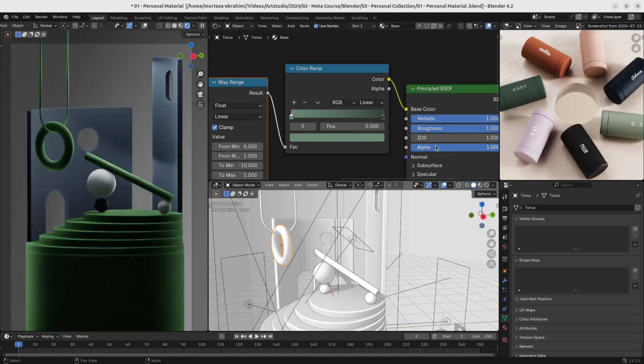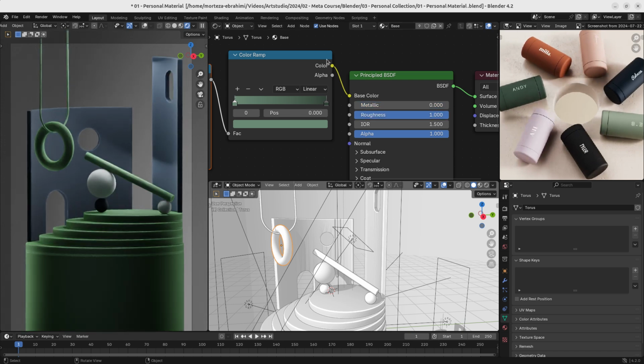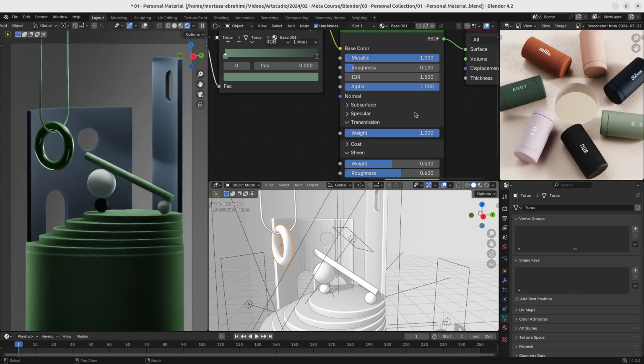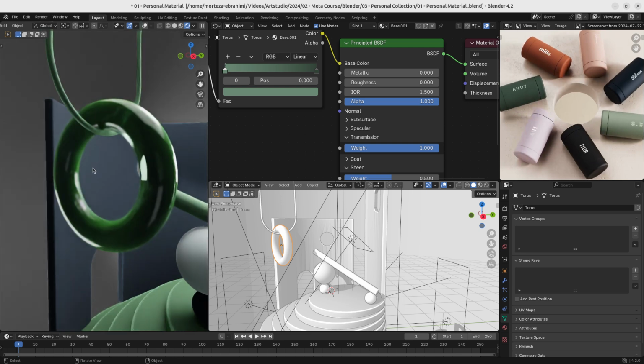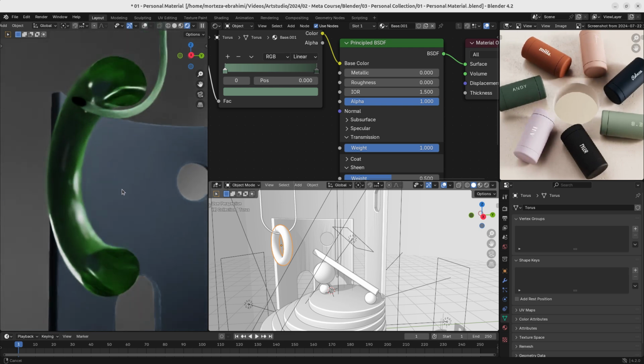Then if you like, you can change this kind of color to any color that you like. For example, we can make it metallic and we take down the roughness. Oh, but before, let's select this and make another color out of that, metallic, and make the roughness really low to see the shininess. Then we can work on the transmission, but the transmission doesn't work with a metallic. Transmission will make the objects glassy. So if I just focus on it, you will see that it is actually converted to a glassy shape, and we even can't see through it.